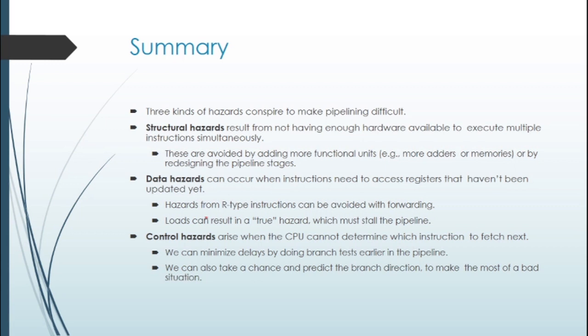Similarly, we have data hazards, where the current instruction is dependent on the previous instruction, and some can be resolved by only forwarding, while for others we have to insert stalls to make it work properly.